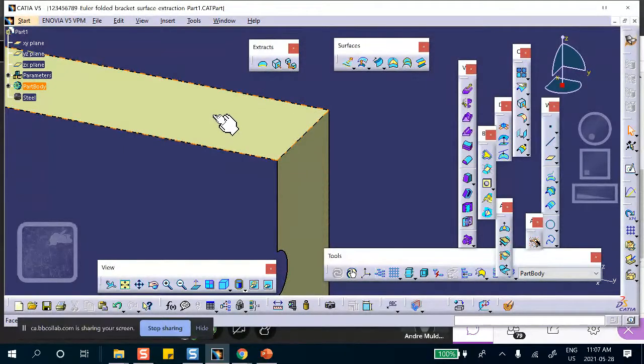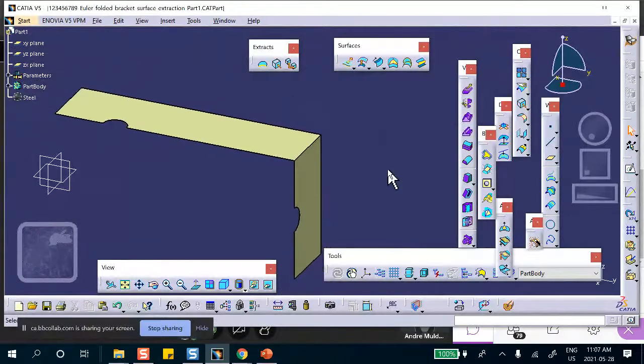When you mesh the top, it's going to have nodes on the top line. When you mesh the side, it's going to have nodes on the bottom line, and they don't match. In the way I did it, because there was no top and bottom line, you had identical node numbers from the top or the bottom. If you join it, this problem will go away.